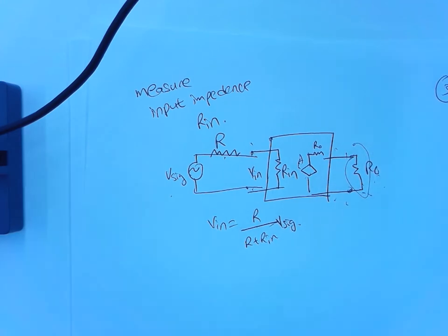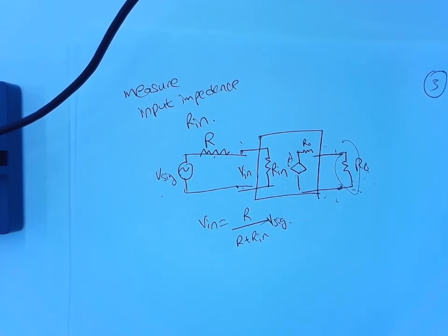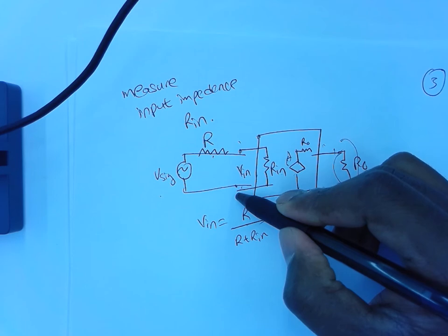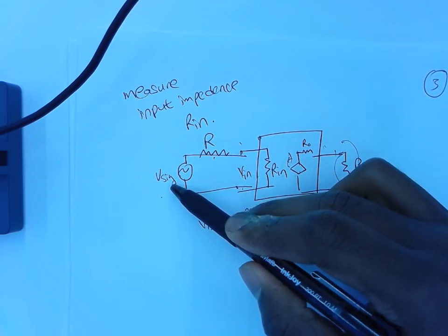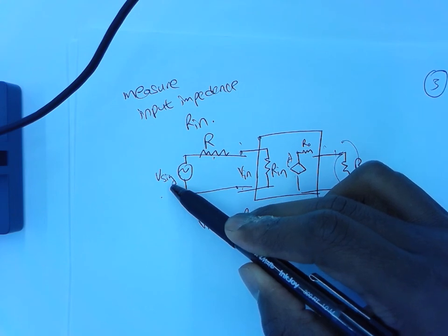So when we were finding what input impedance was, you're saying measure across those two leads with a multimeter and then do your calculations? The input resistance? Yeah, measure across this point and this point what the input voltage is. So you know what this is because you just set it on a function generator. Okay.